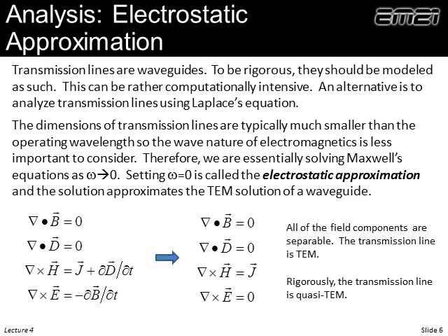Well, what do we buy for that? A lot of speed, efficiency, and simplicity, and for the most part, transmission lines are really only ever used with that TEM mode. It's rare to find them used with other modes, although it does happen.